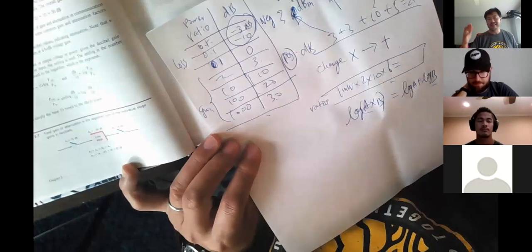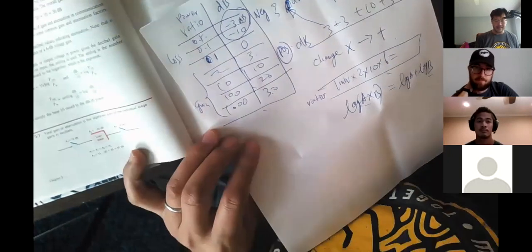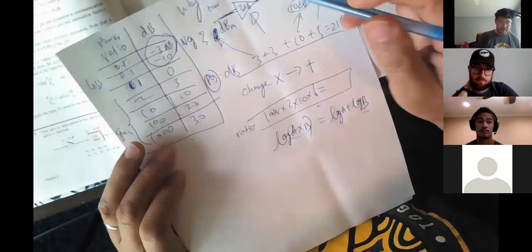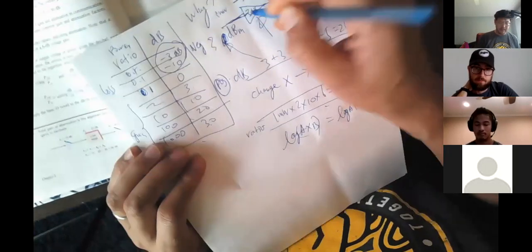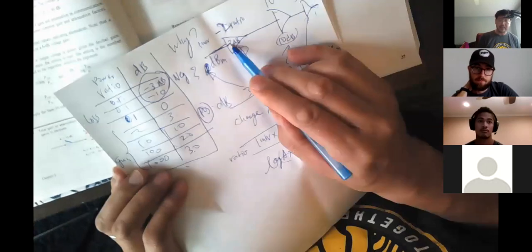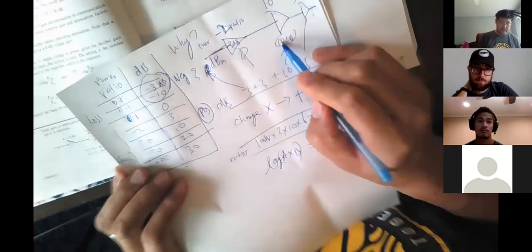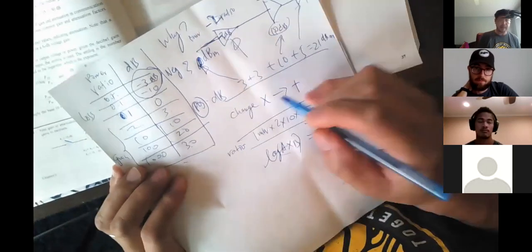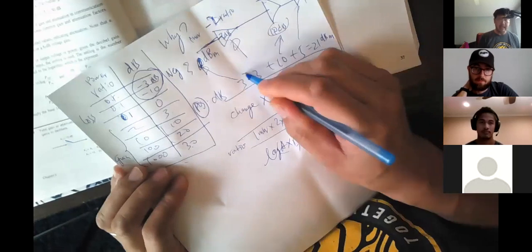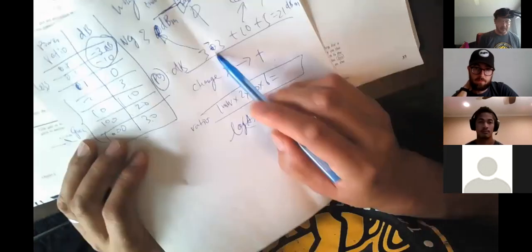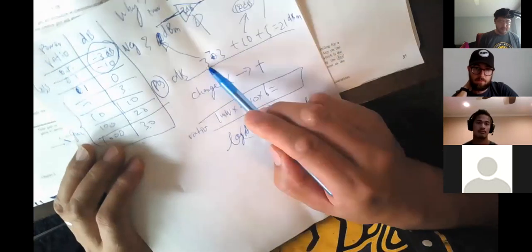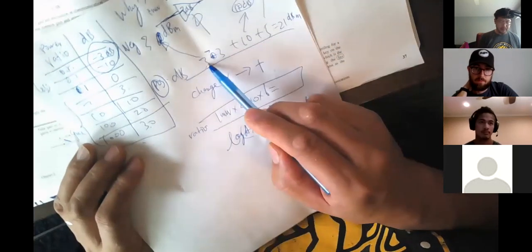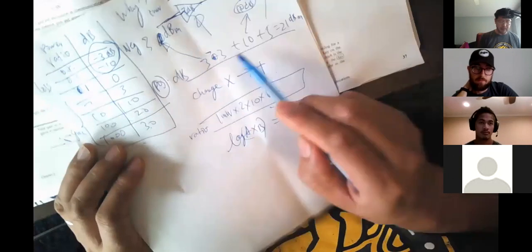Yeah, negative, we subtract. So if this filter, for example, is negative 3 dB, positive 10, positive 5, negative 3 dB. So all we do is subtract here, instead of addition on the second device. So we started with 3 dB, negative 3, positive 10, positive 5.